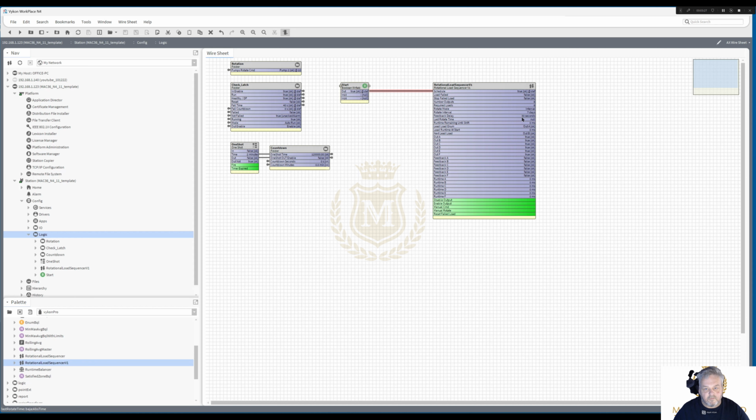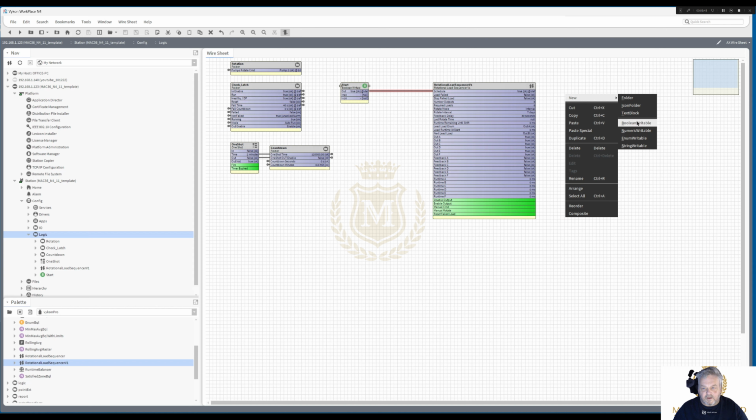They're going to fail after 30 seconds because we've got nothing on the feedback coming in on A, B, C, D, E or F. So that is going to fail very shortly, and we don't have the runtime, so really we need to put the runtimes in of them running. Let's just do that quickly.